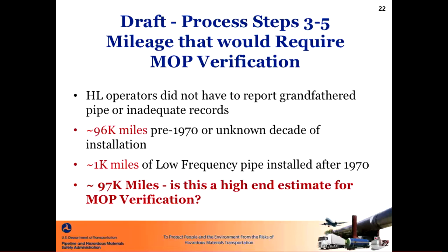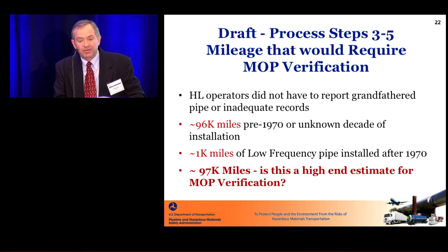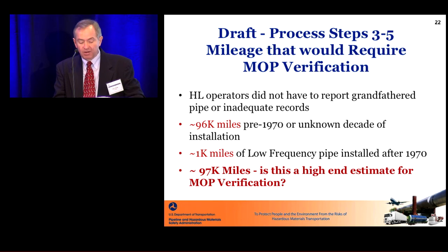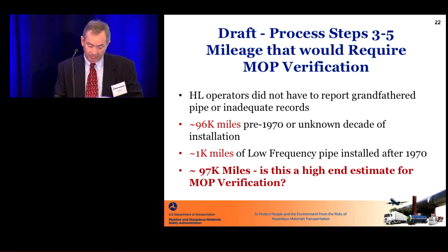liquid operators did not have to report grandfathered pipe or inadequate records. Of course, you don't have grandfathered pipe, but you may have the risk-based alternative type pipe. We know there's about 96,000 miles of pre-1970 or unknown decade of pipe installation. So, I would hope that the issues we're talking about here are the pre-code issues. I would hope operators would have MOP records, whether it's test records or material records, on post-code pipe.